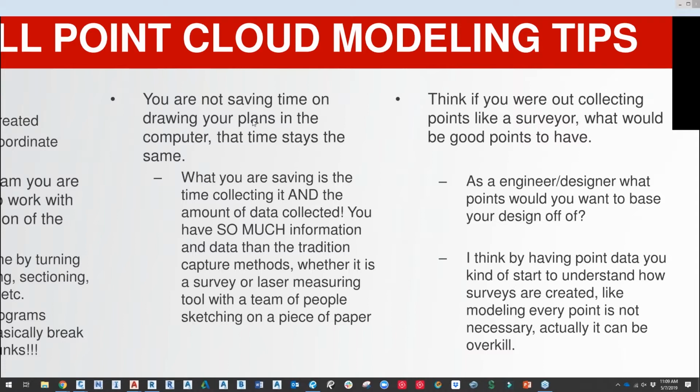So basically, you're going to be collecting the data, so you're not necessarily saving time on drawing it. You still have to take that information back and trace over it. There are some automated tools, which we'll talk about a little bit, but don't think of it as a magic button where everything is created for you off a point cloud. It's not going to happen. But it does save a lot of time, and it gives you much more information than you're probably used to getting in a normal survey or as-built.